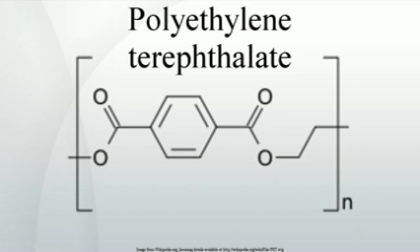Depending on composition and impurity level of the input material, the following general process steps are applied: bale opening, briquette opening, sorting and selection for different colors and foreign polymers, especially PVC; foreign matter removal of film, paper, glass, sand, soil, stones, and metals; pre-washing without cutting; coarse cutting dry or combined with pre-washing; removal of stones, glass, and metal; air sifting to remove film, paper, and labels; grinding, dry or wet; removal of low-density polymers, cups, by density differences; hot wash, caustic wash, and surface etching, maintaining intrinsic viscosity and decontamination; rinsing, clean water rinsing; drying; air sifting of flakes; automatic flake sorting; water circuit and water treatment technology; flake quality control.